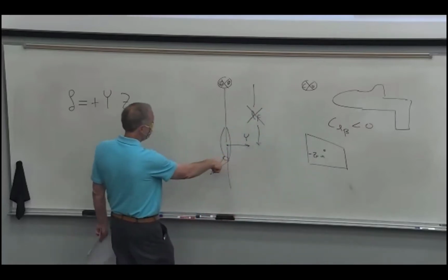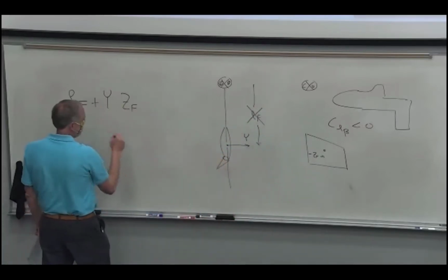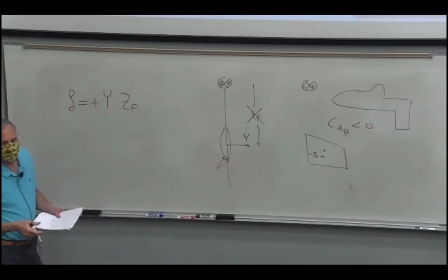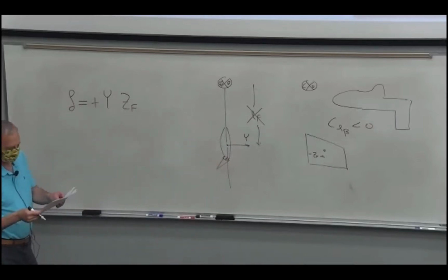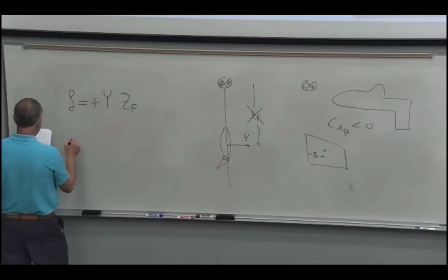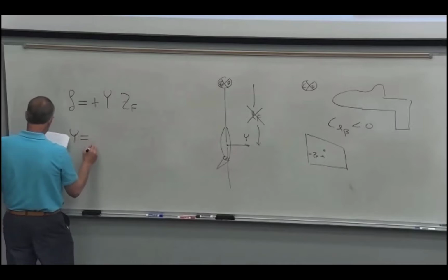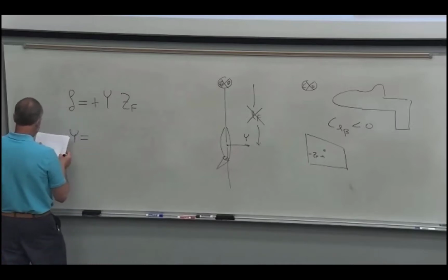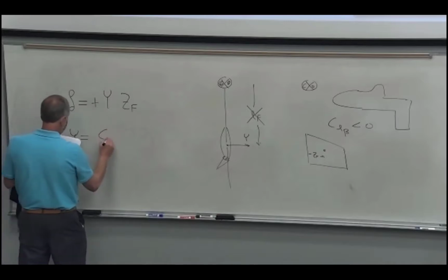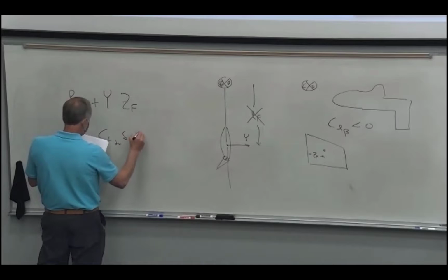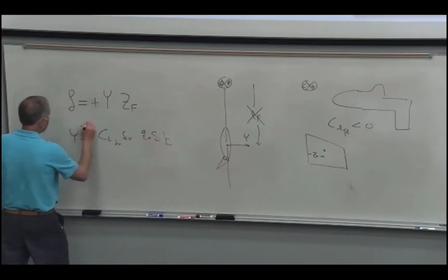Again, this is not anything to do with stability. This is the roll due to rudder, and it's just the effect that you get from the rudder. It's the pilot control, not stability. So this gives you the moment arm, and then you need to do the side force, which is the CL due to the rudder times Q infinity SB, and then you move forward from there.